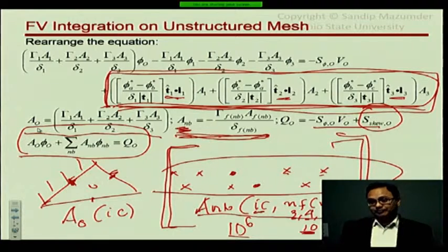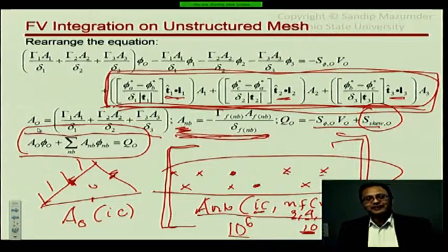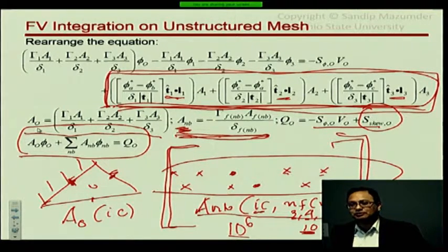Is there any algorithm or method to number the cells in a way that makes the matrix more banded? Yes, people have tried that. It's very difficult to do, especially in 3D; it's almost impossible. And the thing is, even if one element is beyond the banded structure, that's it. Your algorithm is out the window.